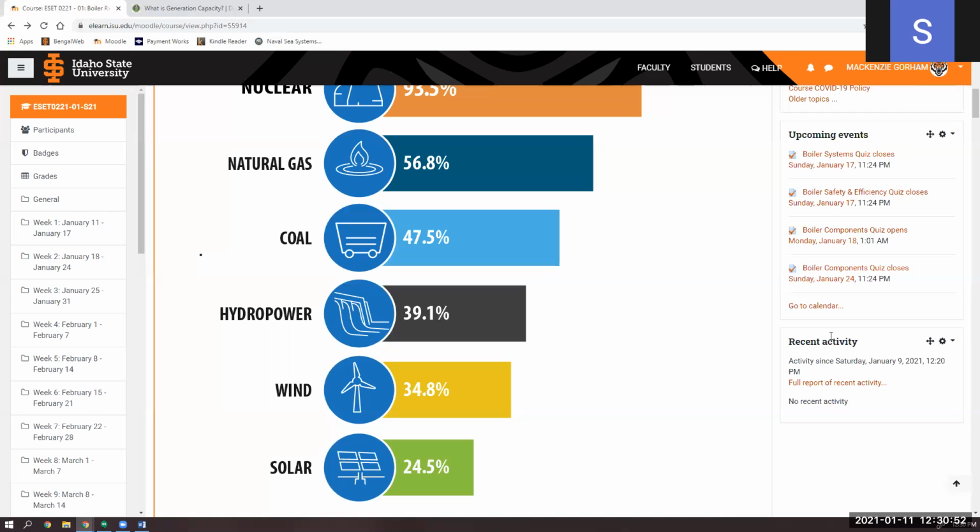But what our electrical grid tends to do, that nuclear power plant is on 100% power as much of the time as possible. And then we'll plan to start these up in the morning before people have demand, taper them off a little bit in the middle of the day, bring them back up for the evening, and then taper them off at night. And we'll plan those very specific power movements. And then if we have a little bit more sporadic use, we'll use something that's a little bit easier to manipulate for that load following. Does that make sense?